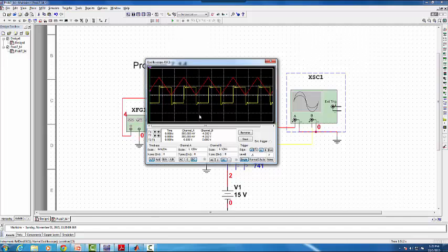And I have a little oscillations going on in here, which just has to do with the stability of this circuit. It's not really the best circuit as drawn. There is a better way to draw that. It would usually have an input resistance and another resistor in parallel with the capacitor, and that would be the integrator. So there would usually be an input resistor to help with some of these stability issues. But truly, the derivative of a ramp should be a step, and that's what we're seeing right here.